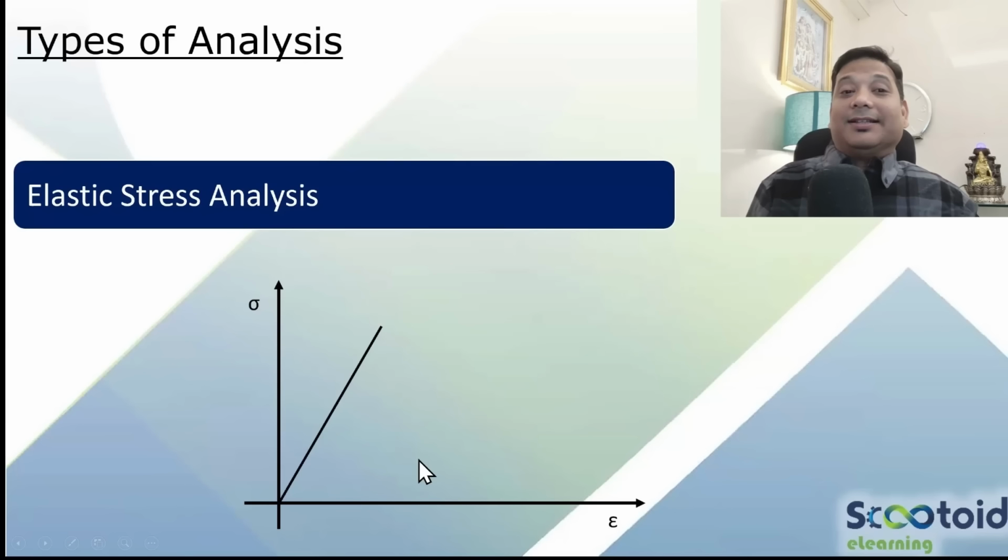Okay. Then how to qualify that? How to say whether my material has passed or failed this analysis? On which basis can we make that statement? For that purpose, we have to classify the loads into primary, secondary, and peak. Peak when fatigue is there, otherwise you don't need.